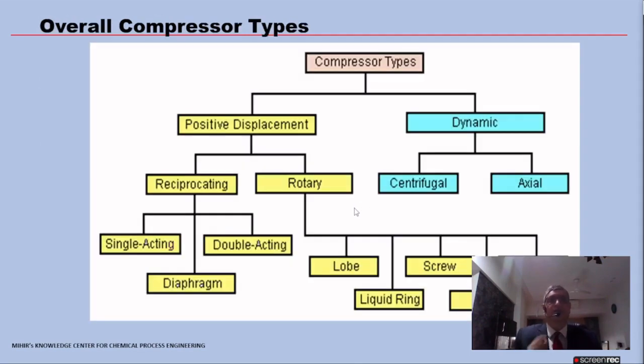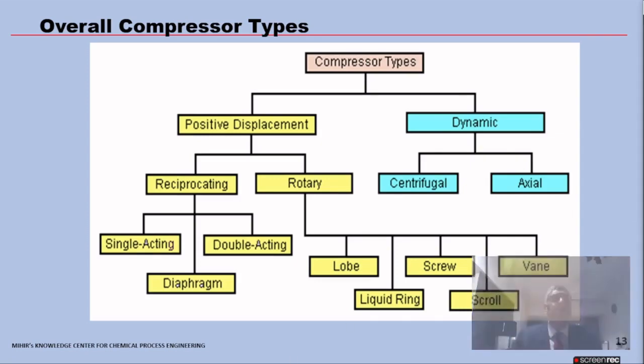Now, overall compressor types, as can be seen. So here in the chart we see the overall compressor types. To arrive at the design of a compressor which will fit the requirements of the particular service, the process engineer is to review the required flow rate and pressure differential carefully, and for all borderline cases should consult a rotating equipment specialist engineer also.